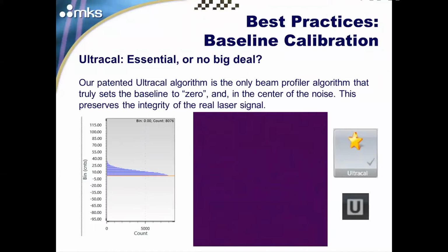So if we just clip off the baseline right now, we still have half of the electronic noise, but as the temperature of the camera changes and the silicon response changes, all of a sudden that other half of the electronic noise starts affecting our measurement. So we want to be able to get rid of that as well.